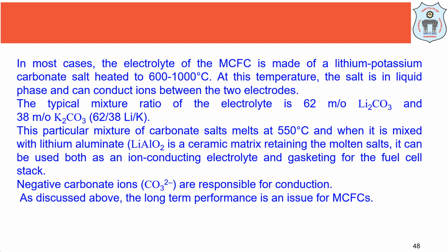Lithium aluminate is also there. We can use a ceramic matrix retaining the molten salts. It can be used both as an ion-conducting electrolyte and as a gasketing for the fuel cell stack. As I told you, the negative carbonate ions, that is CO3 2 minus, are responsible for the charge transfer. Long-term performance is a big issue for the molten carbonate fuel cell, as we have discussed.